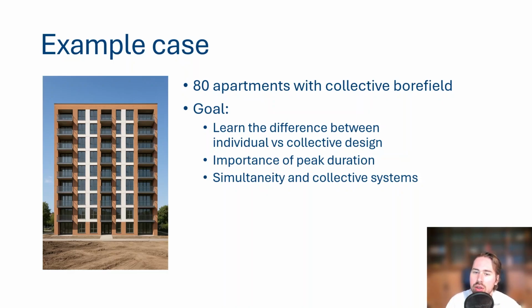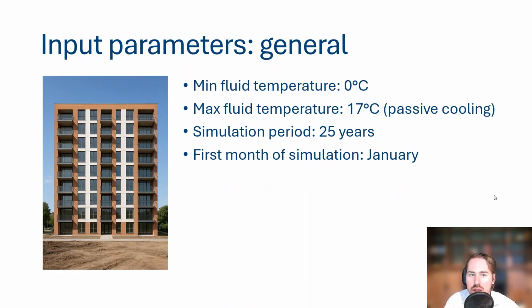So today we will be learning the difference between the individual and this collective design approach. We will learn the importance of the peak duration when it comes to borefield design. And we will talk about simultaneity and how it relates to collective systems. Now, let's first go over all the different input information.